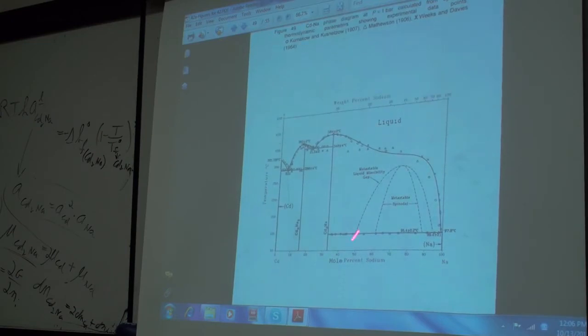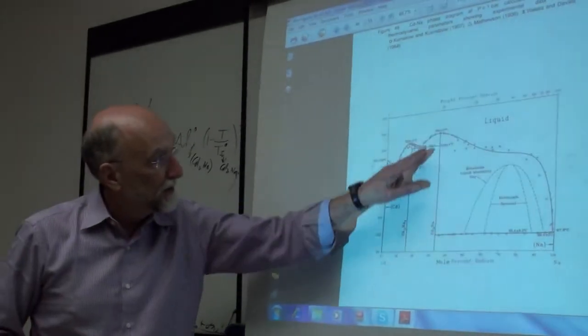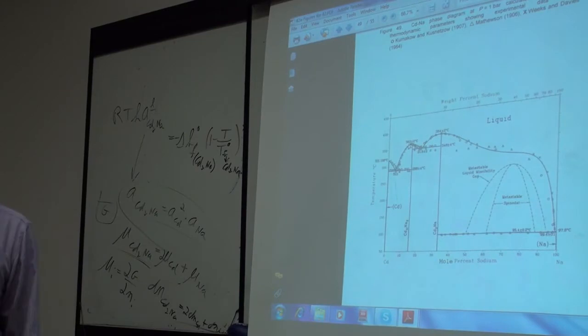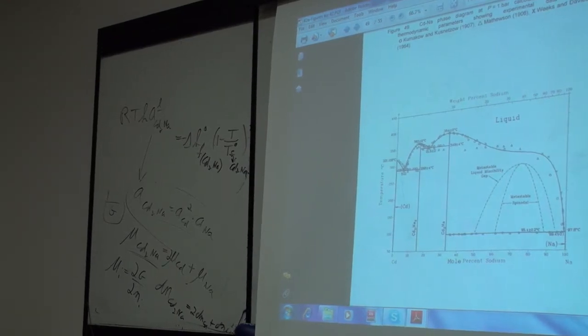Okay, so sometimes you know the heat of formation of this compound, you might know its Cp, you might know its entropy at 298. That'll be different information. So anyway, from this phase diagram analysis, we have no data on that compound, so it's the phase diagram optimization. We're going to back out from the diagram optimization the data for that compound. And what we're really getting then from the liquidus is the heat of fusion of that compound, which can then be related back to the heat of formation of the compound from the definition.